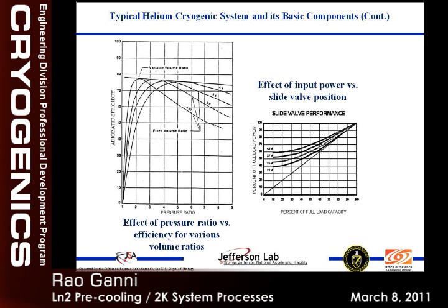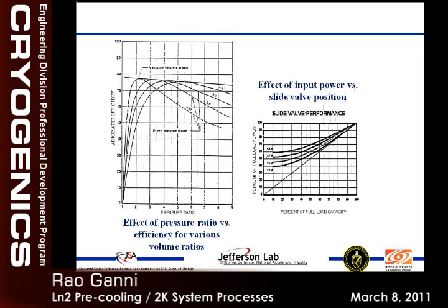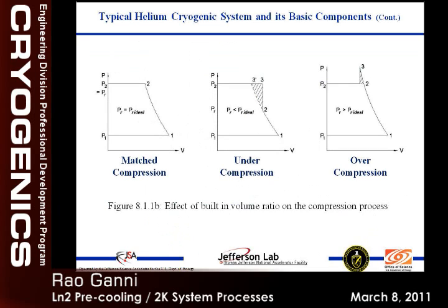And all these factors are, yes? Do you have a buffer time to avoid situation number 3 happening? You cannot solve this with a buffer because it is in the screw. See, you have a port where the exhaust port opens, it's called the final volume. You start with the initial suction volume and where it compresses to.